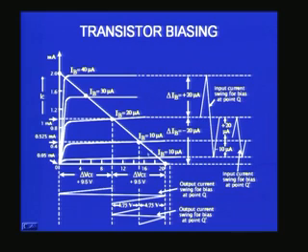And so I have shown here with the load line, if this is the biasing point and I have a signal like this, that means what? The signal corresponds to IB equal to 20 microamperes, and it goes up to, let us say, IB equal to 40 microamperes. That means it is changing IB by nearly 20 microamperes. Similarly, on the downside it can go down to this point.